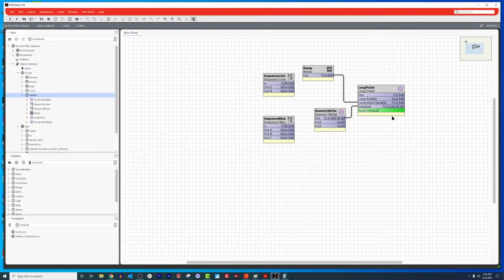If I do need the derivative, it's going to be a tiny little bump to offset my integral, but I do not want to match my derivative to my integral, because by doing that I'm actually counteracting my integral completely. Derivative should be to shave the highs and the lows off of integral. So when you peak on integral, you shave a little bit off of it with derivative. When you bottom out on integral, you shave a little bit off with derivative. It makes your reaction a little smoother. But in reality, most of us do not need to use that in our loops.